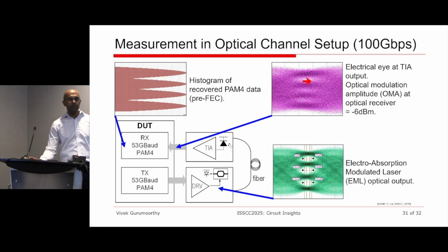You can see it's pretty noisy, right? This is happening at 100 gigabits per second. But you take that and do all your magic inside the DSP chip, and you will recover the 4 levels that you need. Essentially, these 4 histograms are the 4 levels in your PAM4 eye, like -3, -1, +1, +3. As long as you're able to distinguish between the 4 levels, you have recovered most of the eye. And along with this comes the bit error rates and the digital communication theory, like forward error correction and all the other stuff which makes this possible.